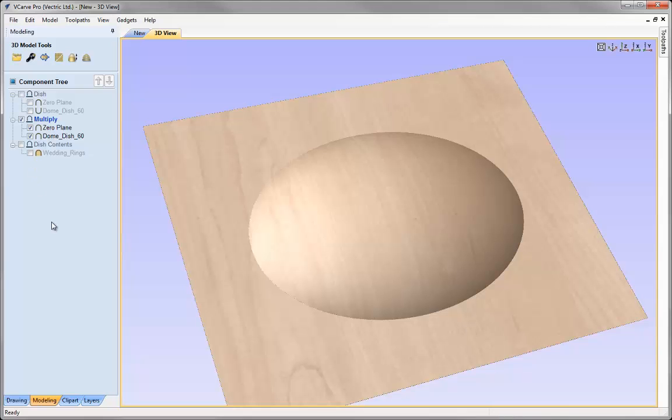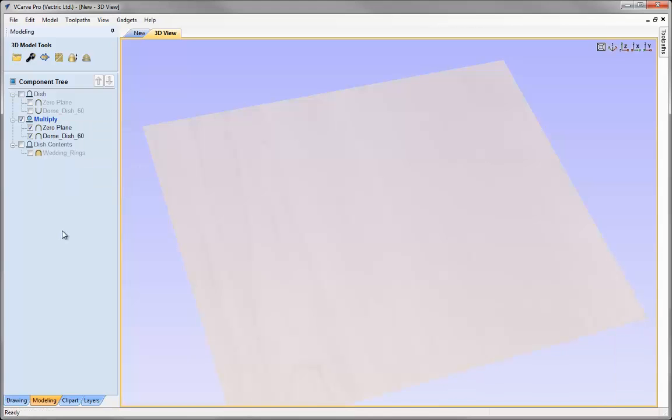So I say this is quite a difficult concept to understand, but if you follow this process of adding in a level, duplicating the components from the first one here, changing this so that it's a 1 inch high dome, then this will work correctly. So it's important now though that we change the combine mode for this level by right mouse clicking on it and change that to multiply.